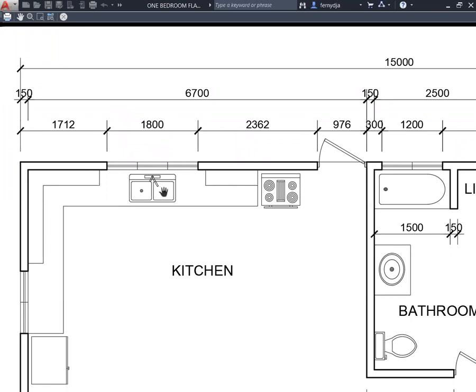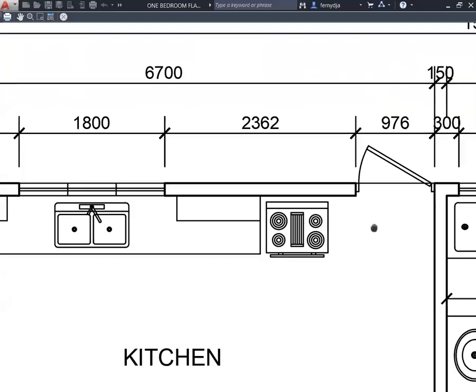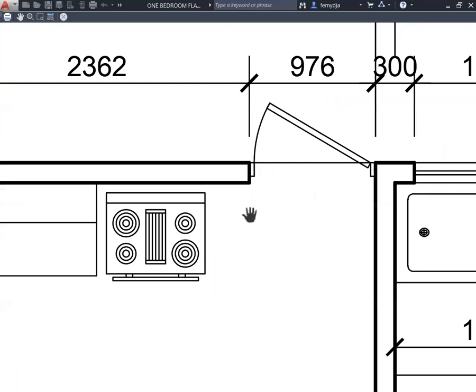Everything looks nice and clean, right? Because we're using monochrome. And the line weight for the wall is heavier than the other ones, and that is because we cut through that. So when you cut through something, you will put a heavier line weight so that it shows as such. We didn't cut through the floor. We are looking down on the floor. So we don't expect the line weight here to be as heavy as the wall. So these were 0.5, but this one was using the default, which is 0.15.